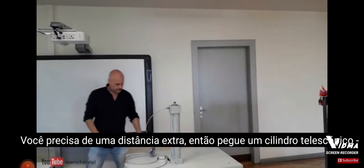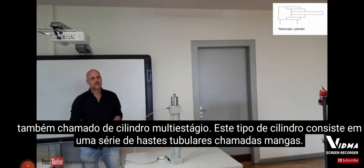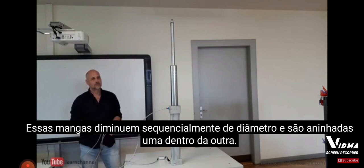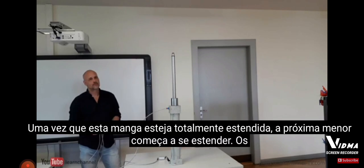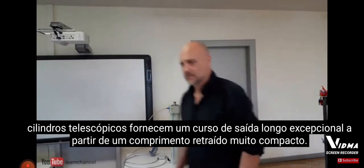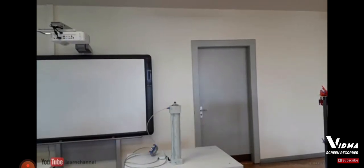You need extra distance? Then take a telescoping cylinder. Also called a multi-stage cylinder, this type of cylinder consists of a series of tubular rods called sleeves. These sleeves sequentially decrease in diameter and are nested inside of each other. Once pressure is switched to the cylinder, the main sleeve first extends. Once this sleeve is fully extended, the next smaller one begins to extend. Telescoping cylinders provide an exceptional long output stroke from a very compact retracted length. They can be designed as single-acting or double-acting cylinders.